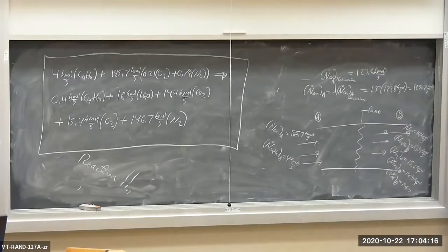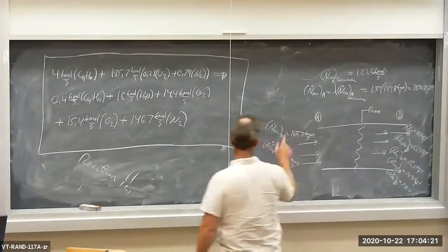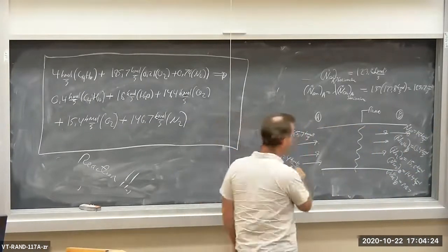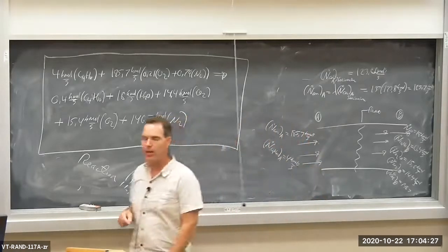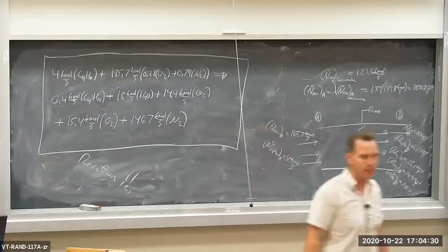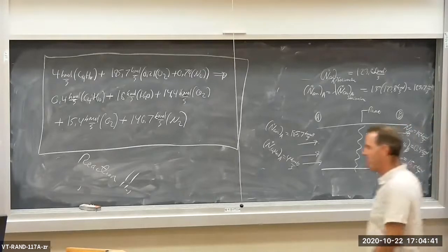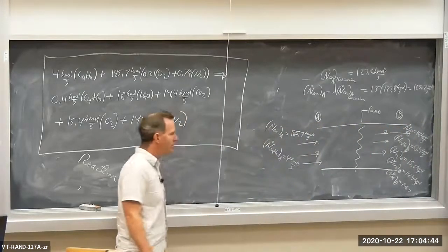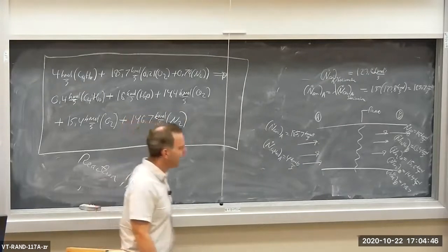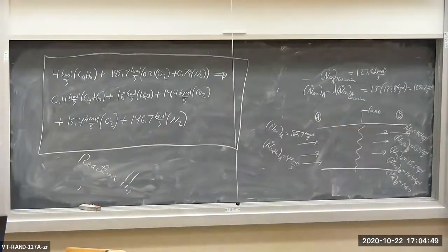So we've got to be very careful how we evaluate the enthalpies for each component in the mixtures, the inlet mixture and the outlet mixture, the reactant mixture and the product mixture. But aside from that, reacting systems are just like any other system. This is just an open system with various mole flow rates of various different kinds of chemicals. There's nothing really special about the energy balance. You're still going to get Q dot minus W dot is equal to dE CV dt plus the sum of N dot H plus on and on. We're still going to have the same old thing.